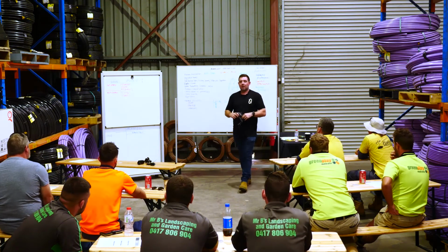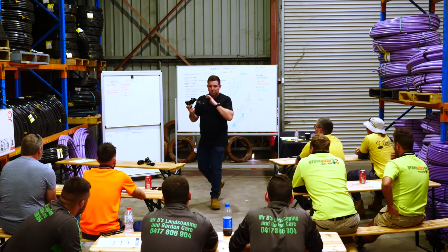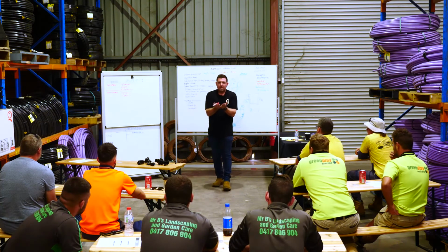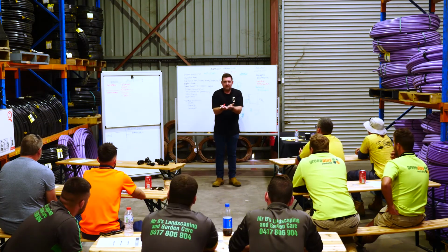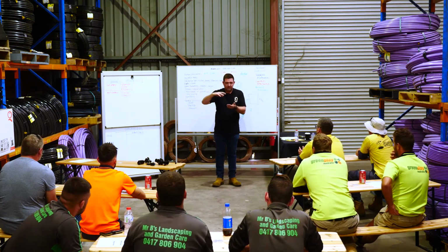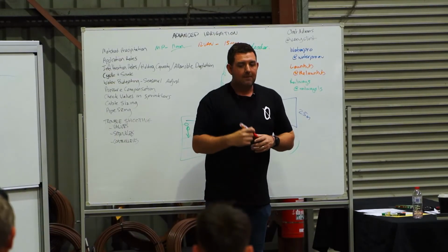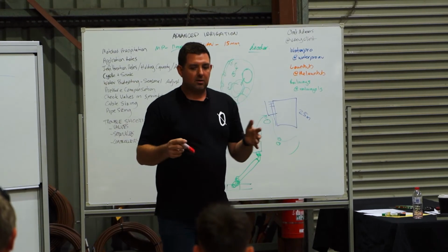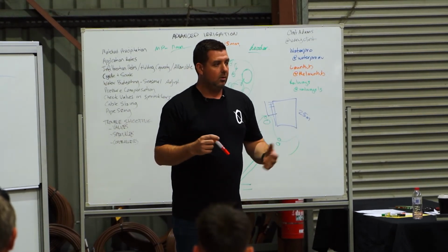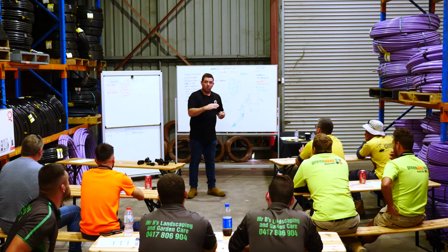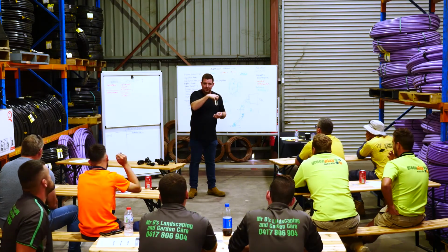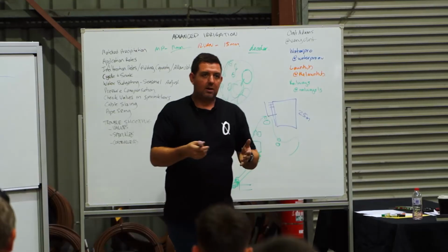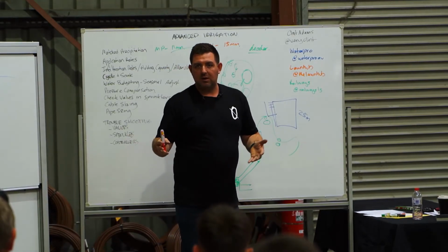Now, electronically with these, as soon as the power gets cut to a solenoid valve, it will close, because the whole operating of it is that the electricity is lifting that pin and dropping it so regularly using alternating current that it holds it up. Hunter nodes, which I'll use as the generic term for a battery operated controller, work completely differently. They're a latching coil. They send a 9-volt pulse to the coil, lift the coil, magnetically hold it open, and then they send a pulse to tell it to close. That's the way that a 9-volt battery can last 2 years in the ground opening a valve.